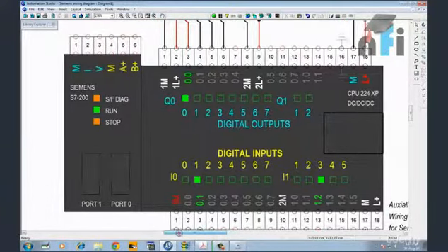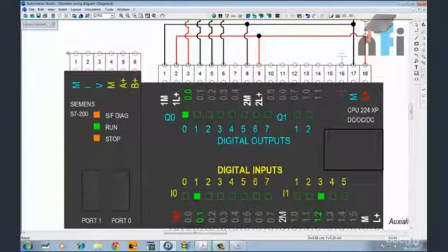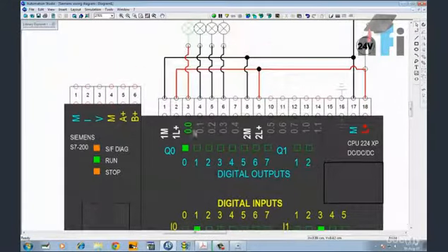And over here, these are the analog input output terminals. We'll have more understanding about these in the analog tutorial. Alright, not in this one. Here we are going to understand only digital inputs and outputs. This is for analog, which will give you 0 to 10 volt, 4 to 20 milliamperes, or it can also take these signals to read them.